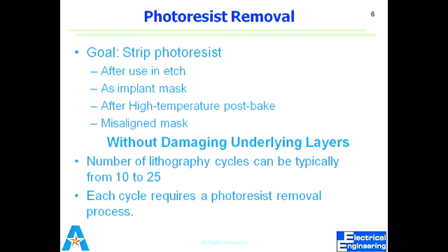It may be a square, but as compared to a square, this gives you better control of the alignment, because if you exactly know that the next layer's alignment marker comes in here, it means that you are controlling in all directions. So this type of alignment marker is put on the mask when you know that more than one layer of the photolithography process will be done in order to complete your device.